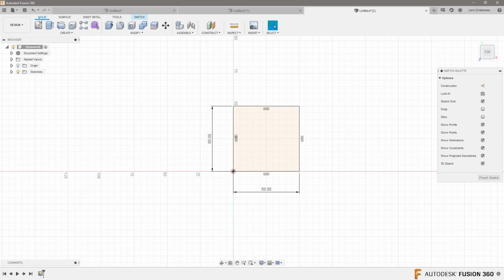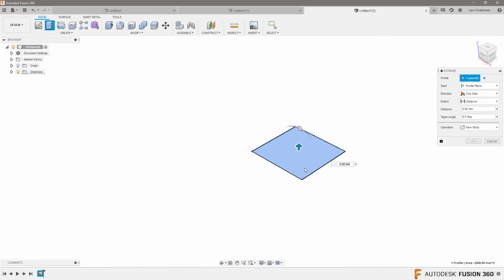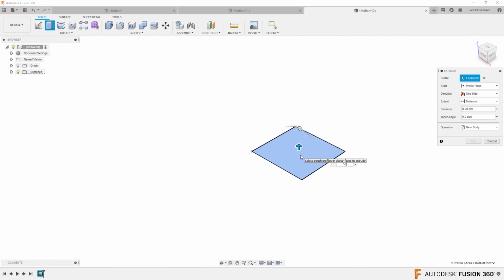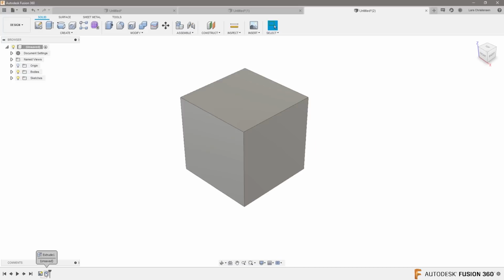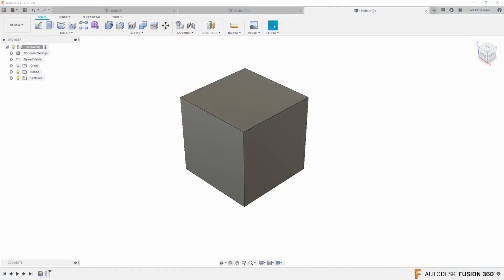And let's extrude it. So we're gonna go back in and do an extrusion, select it here and let's make it 50. So now we have a sketch and we have an extrusion. Now, hopefully, most of you guys out there feel pretty comfortable with this, right? Like, yeah, got this. If you're new to Fusion, even then, I hope that this makes you feel pretty good. A sketch and an extrusion.